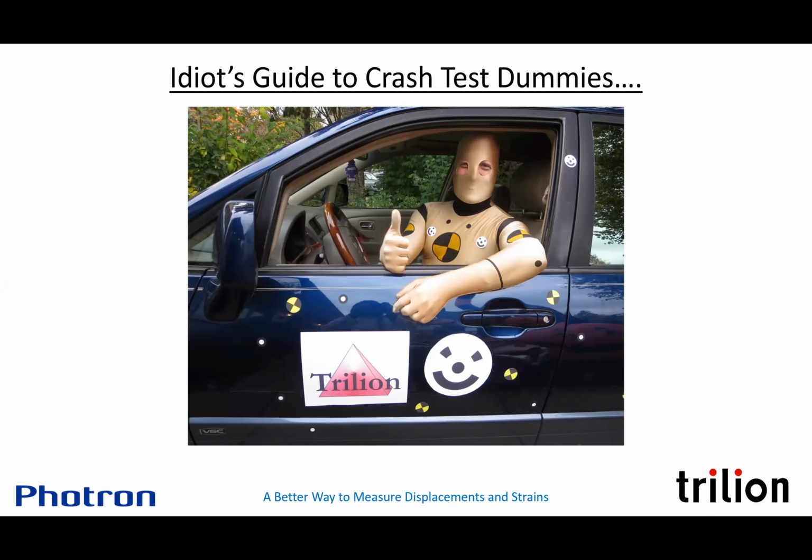Historically, GOM and Trilion, we find the PFV software so nice and easy to use that we didn't feel the need to directly drive the Photron cameras from the Aramis software. In particular, their random one trigger, which we don't see on anybody else's high-speed cameras, makes it really simple to snap and save the calibration images and then import them into the Aramis software. And we can do that with any what we call external camera.